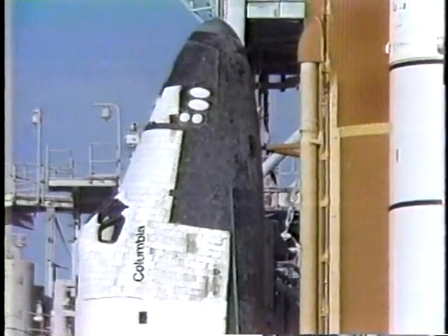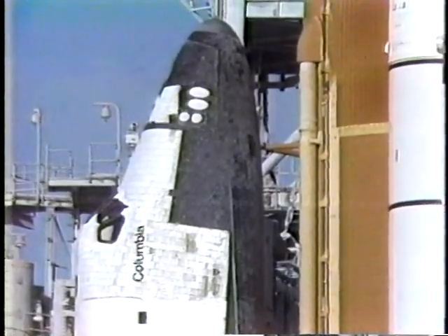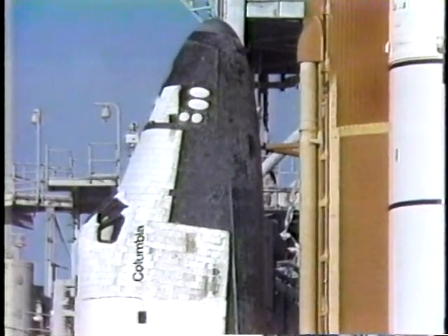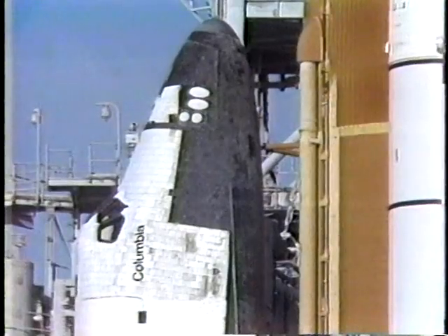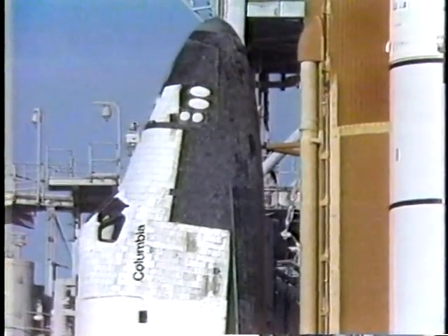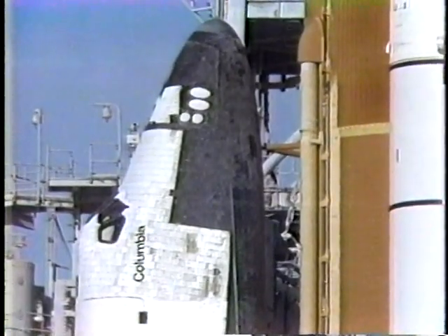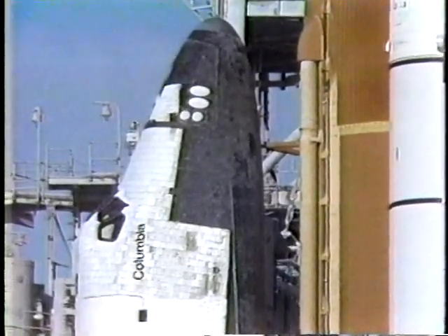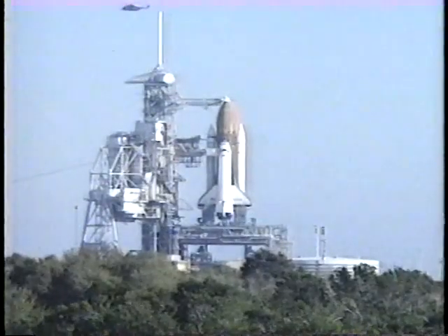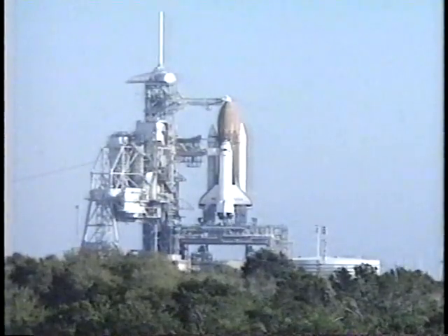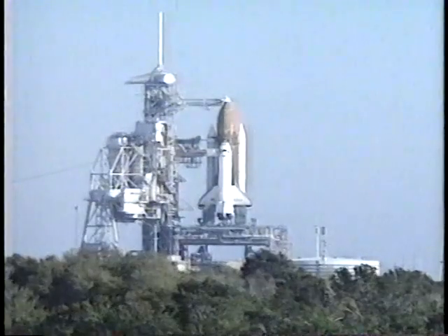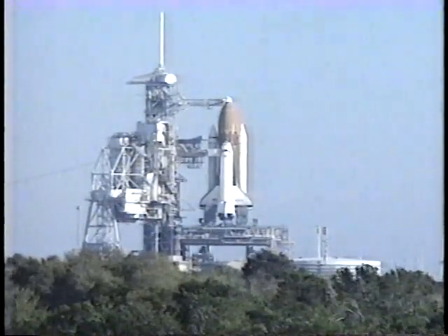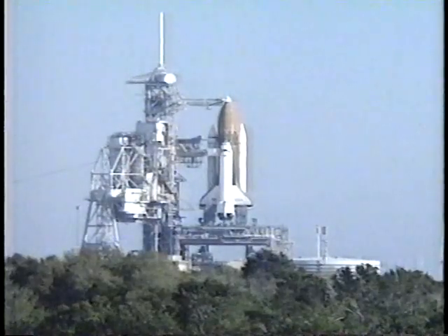After T-minus 20 minutes, all problems or trends that require a countdown clock hold will be reported to the NTD on channel 212, together with a recommendation. After T-minus 5 minutes, any hold, manual or GLS, should be accompanied by a description of the problem and a recommendation. The count clock will continue until T-minus 31 seconds unless the recommendation to hold the next milestone is necessary. Are there any questions? That concludes the briefing. All personnel to OTC. After transition to Ops 101, discontinue all LDV PMU reads for remainder of countdown.